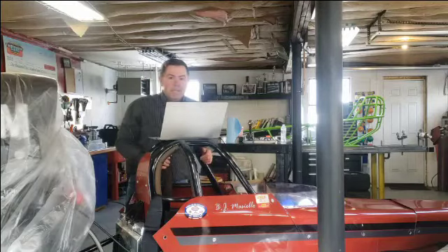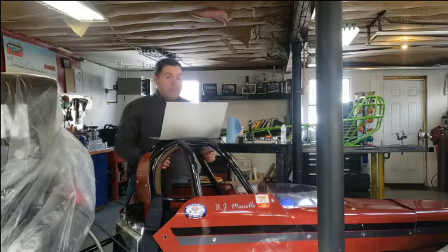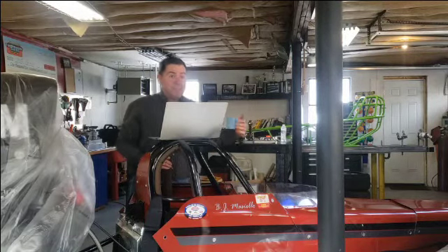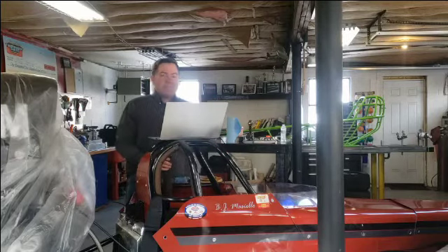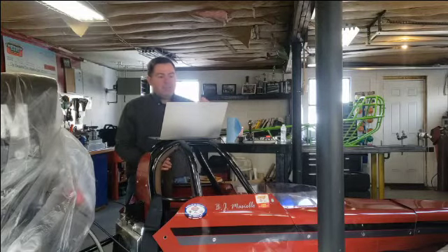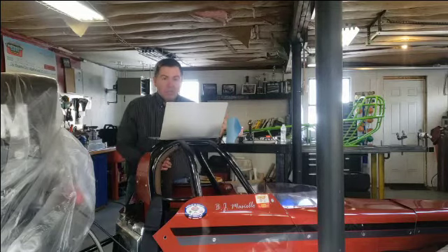Right now my setting is 1 millivolt, representing every 100 milliamps of current flow. The numbers don't really matter because we're not looking to take a perfect measurement of current flow. All we're looking to do is to be able to see that change take place when I close that switch and the fan turns on.